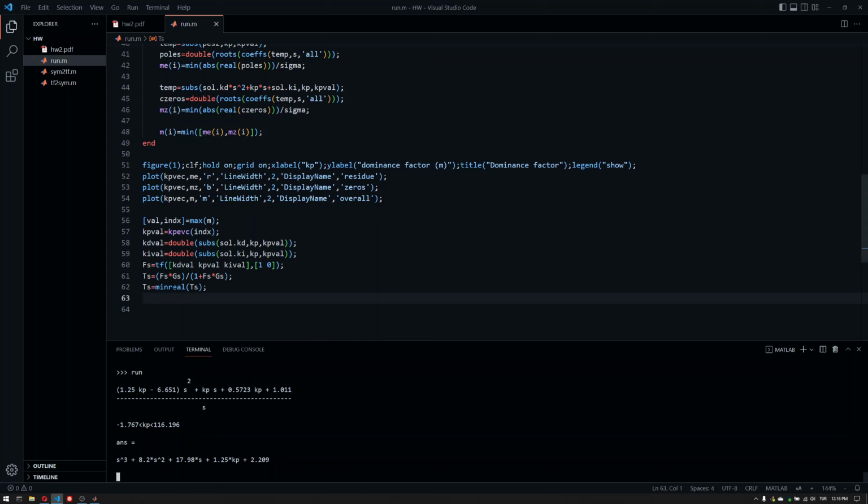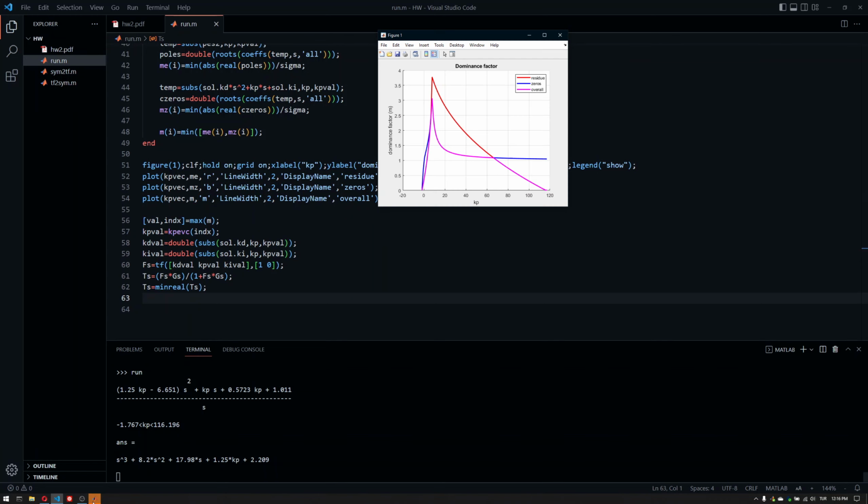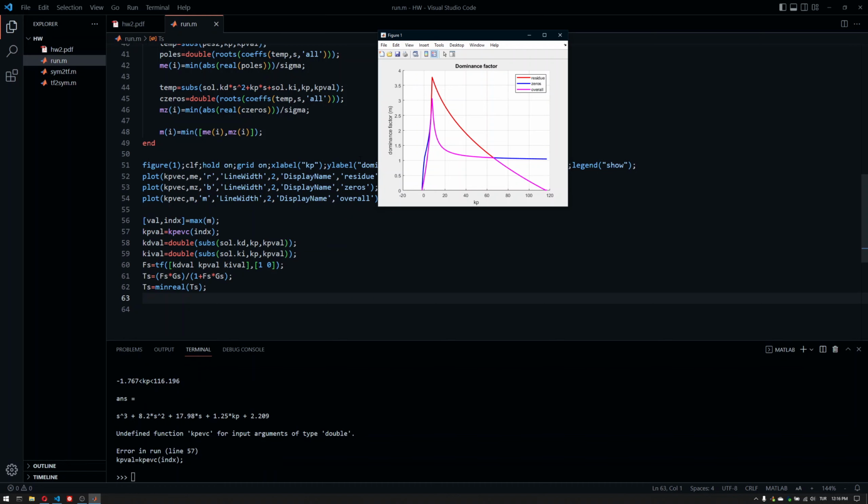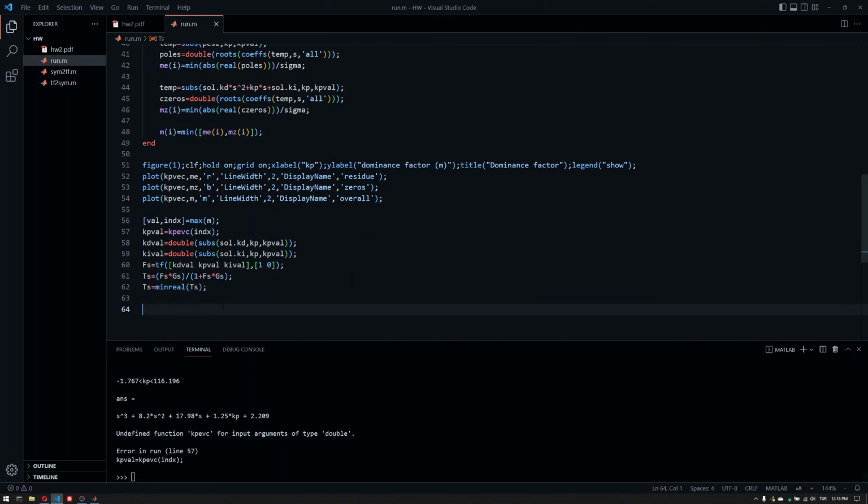If you don't call minreal, and if you call pzmap, for instance, you will still see the pole zero cancellations on the plot, on the graphic, which is not quite nice, because they don't actually exist, because they are cancellations and you should get rid of them. If you are purposely canceling out something, that is another story. But if you're just using the feedback connection and try to calculate it, then there's no pole zero cancellation there.